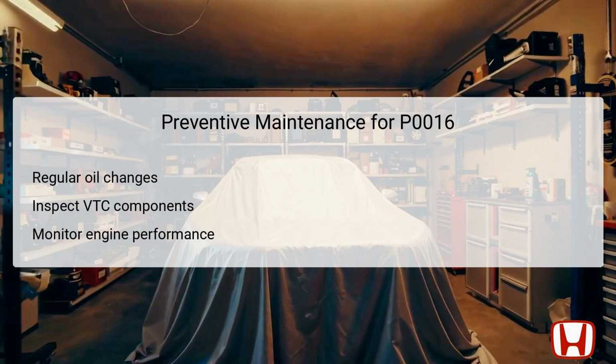Additionally, it is vital to inspect the variable timing control, VTC, components periodically. Checking the VTC oil control solenoid and actuator is essential to ensure they are functioning correctly and not obstructed by debris or oil sludge. Monitoring engine performance through routine diagnostic checks can help catch issues before they escalate. These preventive measures will help ensure that your vehicle remains in optimal condition and reduce the risk of timing-related DTCs